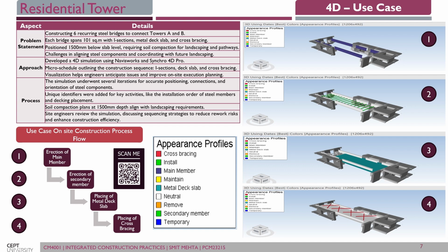The approach is developing a 4D simulation in Navisworks and a Synchro 4D Pro model, with a micro schedule outlining the construction sequence of the I-section, deck slab, and cross bracings.